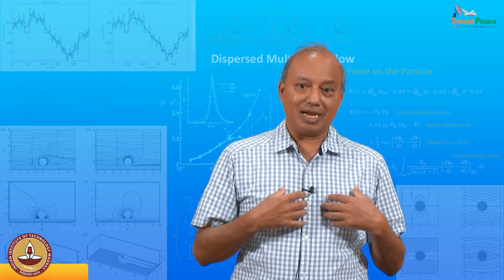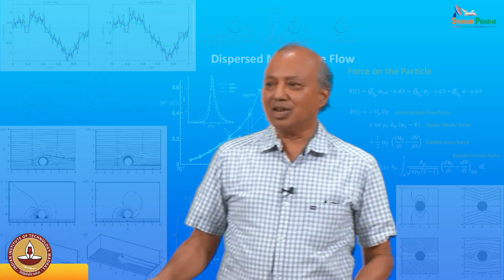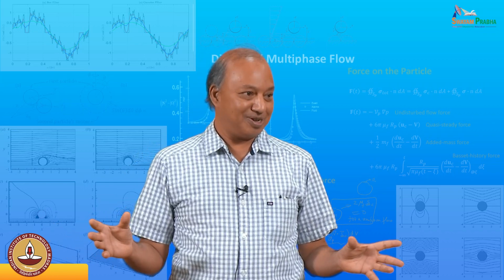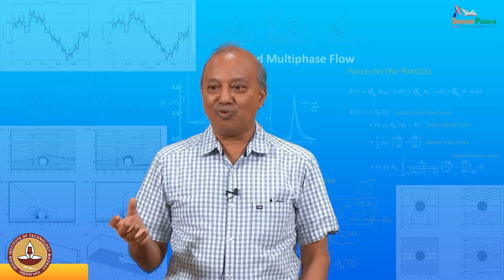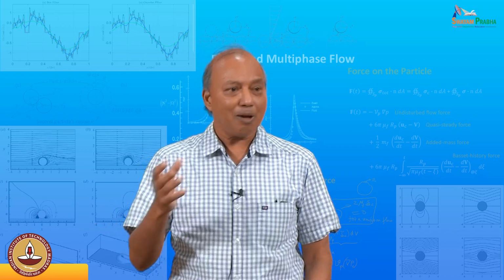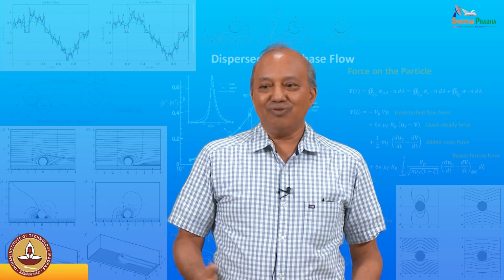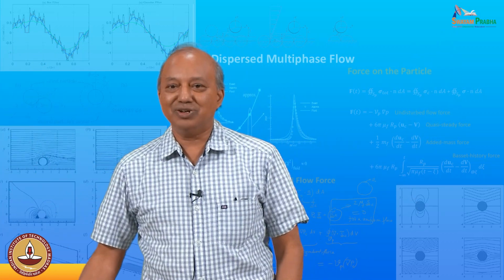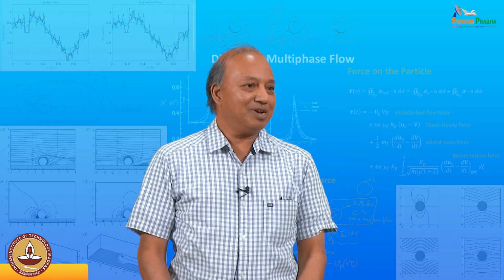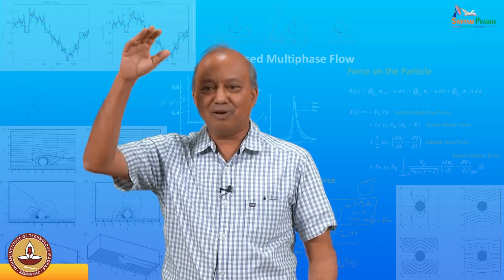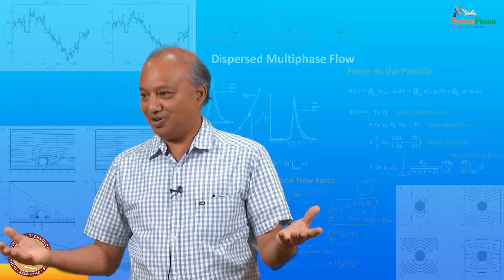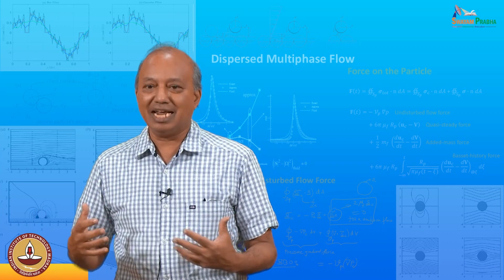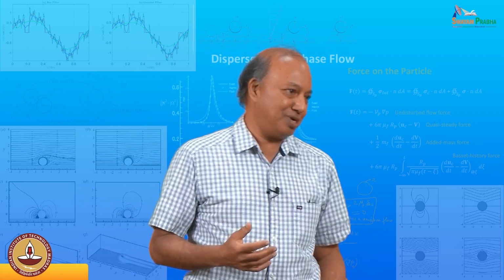Therefore, I personally like volume averaging a lot, sort of like large eddy simulation, where you coarse grain, you still have lots of structures around, but that still has this question: what length scale are you going to average? One simple answer is, you will know how big a grid you can afford. You have a tank of 1 meter by 5 meters, and let us say you can only do simulations of say 100 by 100 by a few hundred grid points. You know exactly what your volume average is going to be. So many times your averaging scale is dictated by what you can compute.